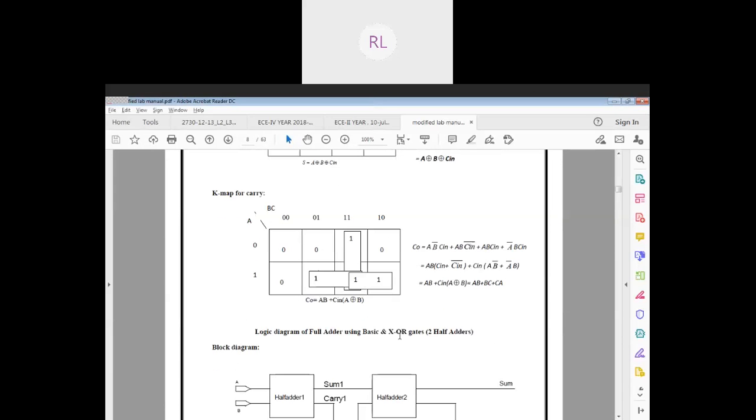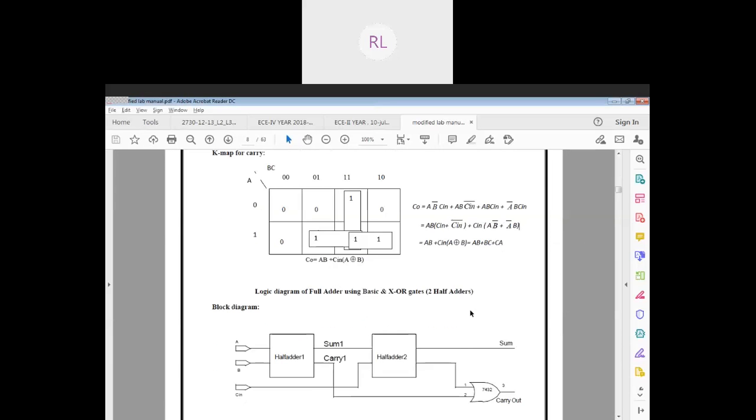So once your K-map is loaded, you can see that I don't have any option to group them, because there is no pair at all. So I will have to just circle them singly and put the equation. So finally I will be getting A XORed with B and XORed with C. So that's my final thing that comes up.